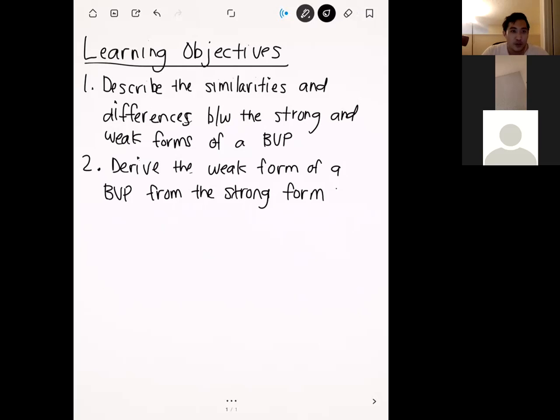And so, just like we mentioned before, everything we've done up to this point is more called direct stiffness method. I like it because I think for a lot of you guys, it's familiar to what you've probably covered in your statics class, but we set up the problems in a slightly different way for finite elements. So we're going to build on a lot of that information. This whole concept of element stiffness matrices, assembly, boundary conditions, all of that's still going to come back. But now we're going to see how codes like ANSYS actually implement their codes.